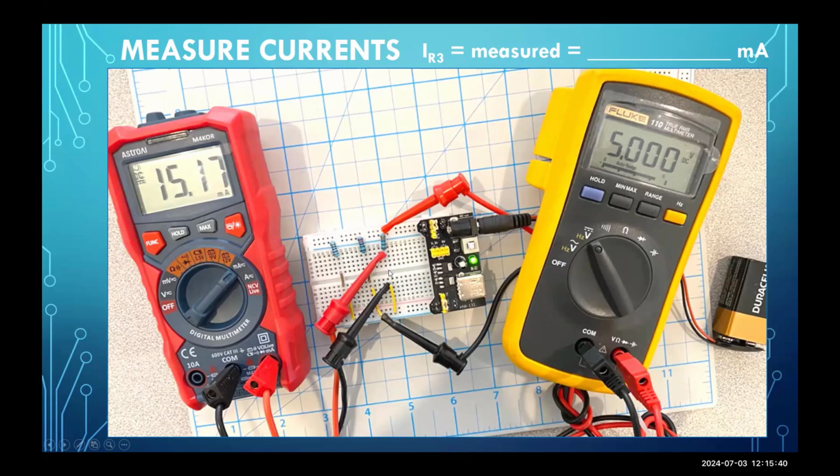I can only have one place in the circuit open at a time when I'm measuring for current. So I've created the open here, and now I'm measuring something pretty close to my calculated value. We calculated 15.15 milliamps, and this is showing 15.17 milliamps, which, with these metal film precision resistors, is pretty consistent results, which is great.